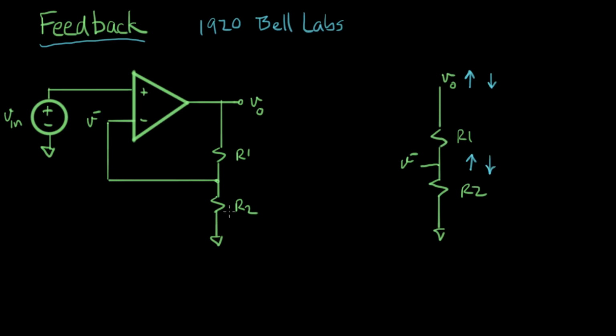So that's isolating just on this part of it. We have no inversion happening around here. So we go around here now, and let's look at what happens on this path here. If we go up in V in, then we know that V out goes up. If we then change colors to, let's try this, if V minus goes up, then V out goes down. That's the inverting path. So there's one inversion in this circuit, and it happens right here where V minus goes to V out. So that's where the inversion is.